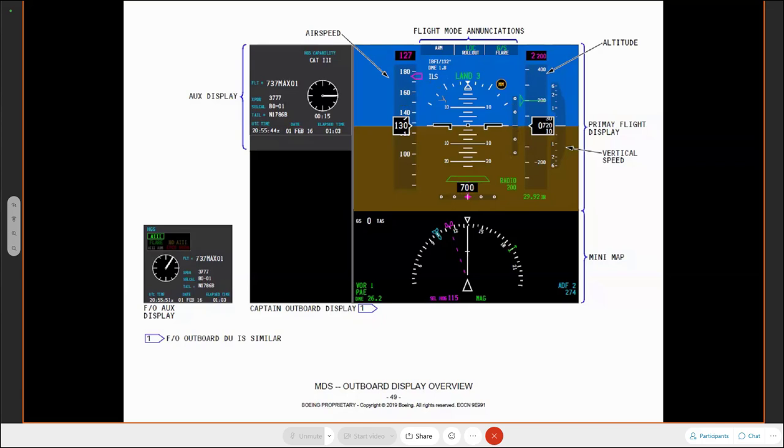A single ground-based augmentation system can cover maybe 15, 20 different runways, and if it's local to two airfields, like here in the UK where you've got Heathrow and Gatwick in close proximity, you could put a ground-based augmentation transmitter between the two airfields and it'll cover both. So you don't need individual glide slope and localizer transmitters at each end of the runway. You just have one system, that's it. So again, a lot cheaper all in all. So it is capable of GLS.